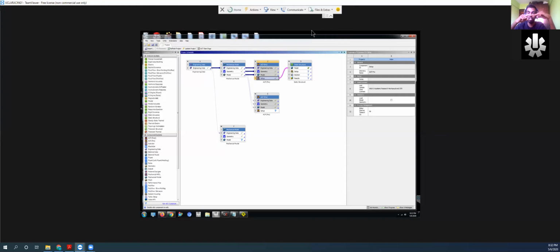That's for solid. For shell, the nodes only travel in the X and Y, so it only happens on the surface of the structure. We tend to use shell with respect to carbon fiber because it's easier on the computer and faster to compute, and carbon fiber is so thin in the Z direction with respect to the X and Y. If you look at the seat, the seat itself is humongous, but its thickness is negligible compared to the X and Y dimensions of the seat. So in this case, we can use a shell.